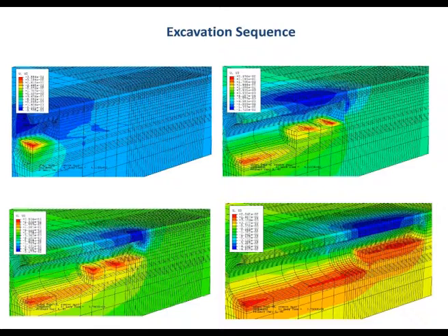If I leave a gap of 2 meters, the effective gap is 9 meters. So what is the difference between 8 to 9 meter effective gap? Honestly, it's not 1 to 2 meters. 1 to 2 meters is a 100% increase. 8 to 9 meters is less than 20% increase. So my point is, why argue over that when in fact the better thing to do is get a shotcrete that hardens as quickly as possible and gives you a high strength. That's what you need.